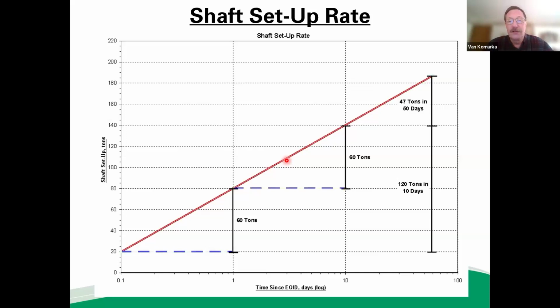The other side of that coin is if someone says, well, we want to test for a lot of setup, let's wait 60 days, even 40 days. Well, we all know what that does to construction schedules, and it adds cost as well as schedule. Maybe the contractor has to demobilize and remobilize. So you can look at this and say, we really don't gain that much if we can restrike at say 10 days or even 3 days. We don't gain that much by waiting another 30 days. The payoff diminishes with respect to what it costs to wait that time. So knowing those two things helps us plan our timing for the setup.